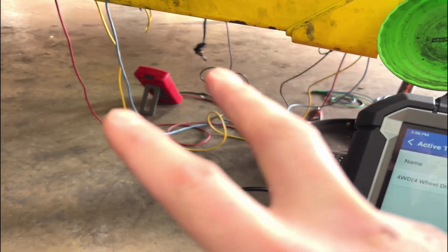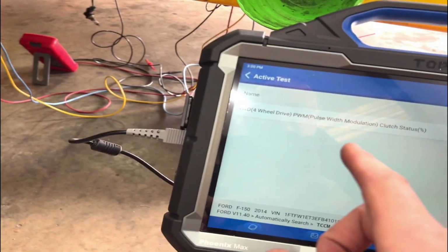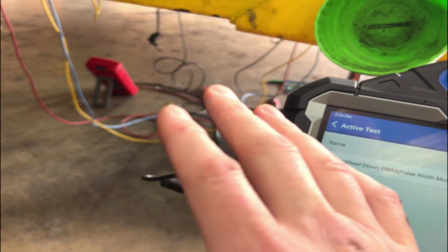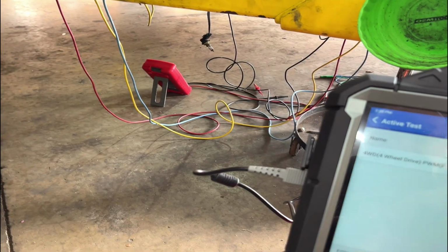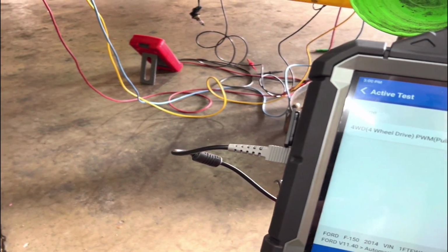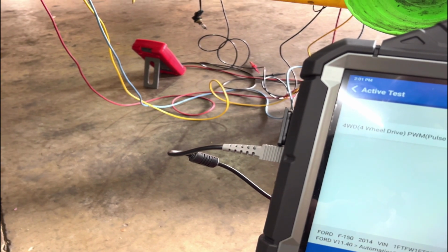If anything, I may have to just plug it all back in if there's another code setting and then cut the motor wire just to be 100% certain, because we really want this code to go away to make sure that's our issue. The 1 point whatever ohms is, I'll also look for a spec for the motor resistance, because that 1 whatever ohms is not open, so we need to be for sure.